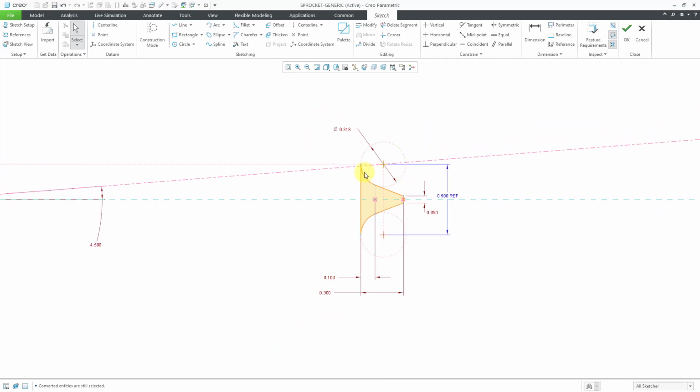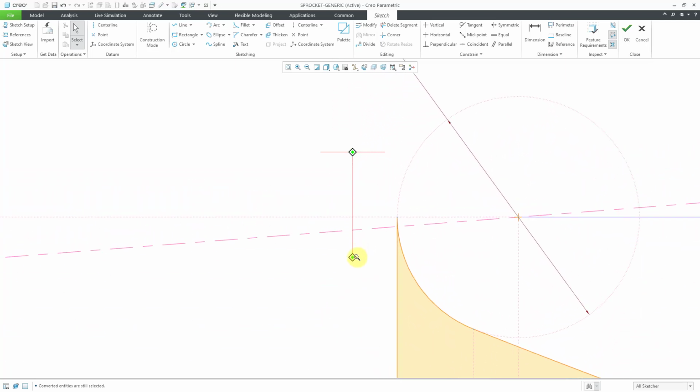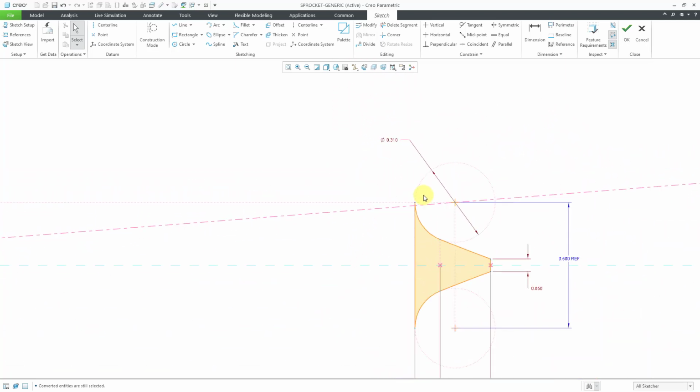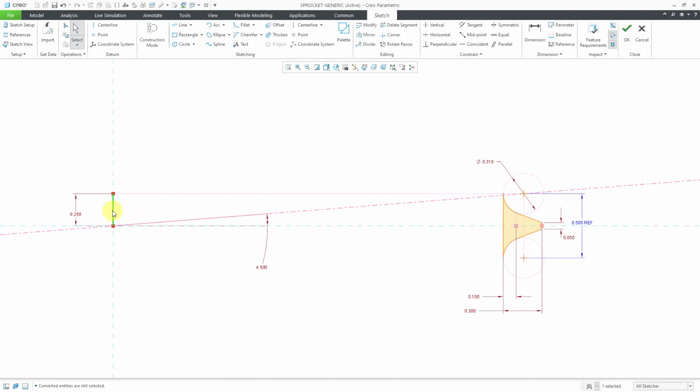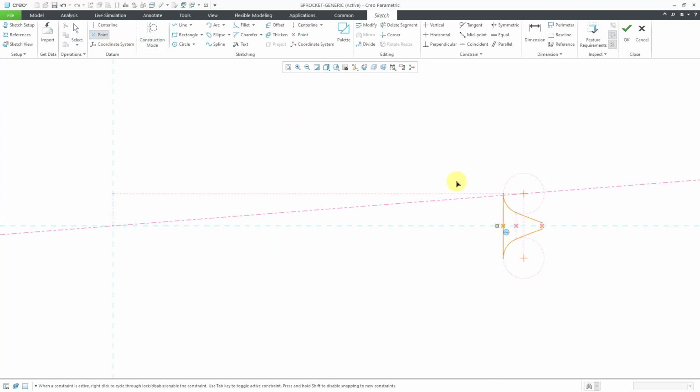One other thing that I am going to put in is that the diameter of the circle that this is going to be attached to is going to be out to this location. And so I am going to give myself a reference for that. I'm going to create a sketch for another circle in a separate feature just to keep everything easy. I've got this one other line over here. Let's turn it into construction geometry. So this sketch has everything for our tooth, but let me put in a point over here just as a reference later on for the next sketch.